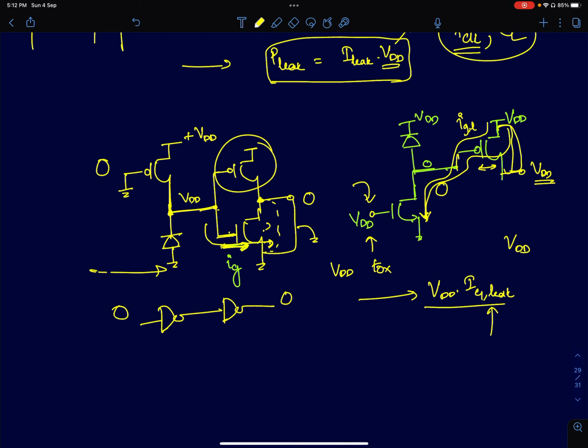of this digital circuit. So leakage power does not depend upon clock frequency, and it also doesn't depend upon the load capacitance. It may have some second order dependence because load capacitance, if you involve parasitics, will be a function of how big the device is. So that might determine some diode sizes. But if I explicitly put a cap on the load, I can say that it doesn't depend upon an explicit additional cap you add on the load.